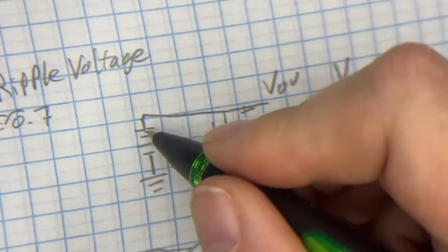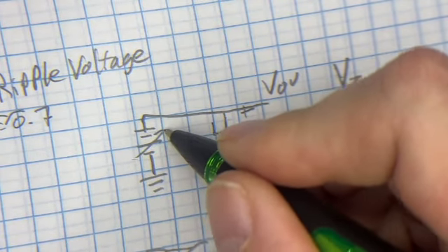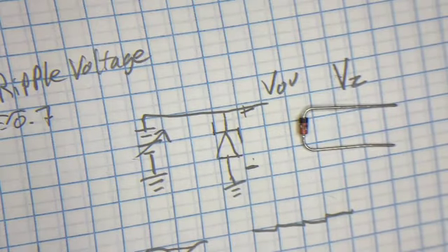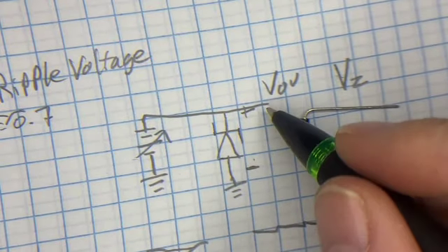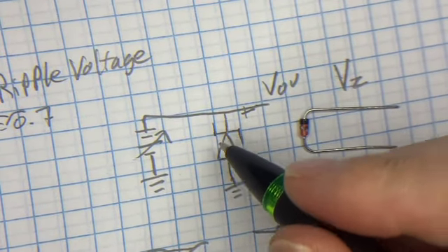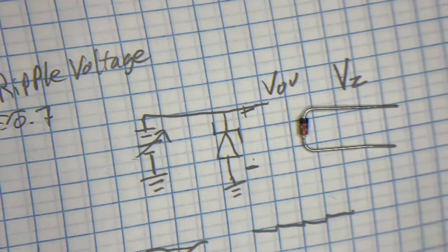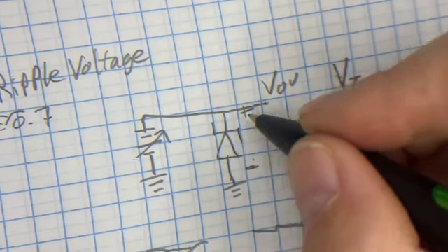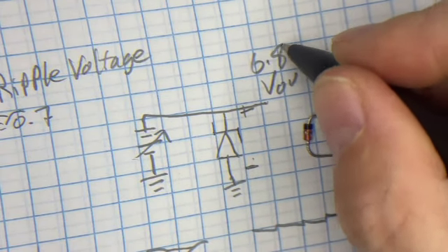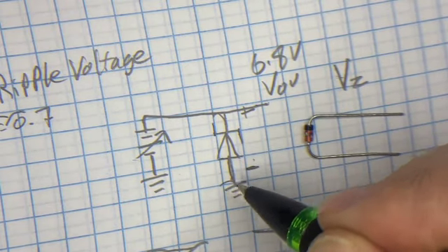The little arrow going through it like that says that it's variable, so we can adjust it, right? So anything 6.8 and below will go straight past this thing and be on the output. Once you get 6.8 volts or above, this will only output 6.8 volts, and all the other voltage will flow through here to ground.